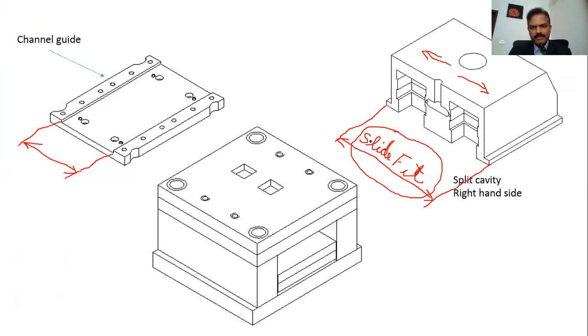If you leave this relation open, like if you maintain a loose fit, the slide can move this way sometimes, it can move the other way sometimes when it moves forward. So the part is getting completed when both sides, the left and the right hand side slides, come and butt on this surface against each other, right? So when it butts, it should make sure it is butting on the same periphery line, the complementing periphery line on its partner slide.